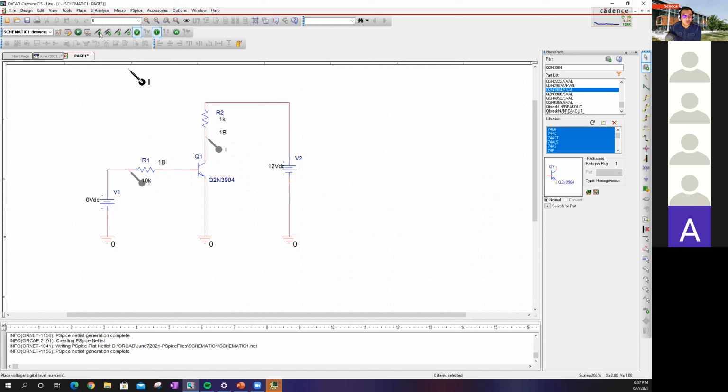And then we also want to know the voltage, let's say the voltage of IB. So we'll put it here, and then we want to know the voltage of VCE. VCE is kind of hard because there's a C here and there's the E here. So we need to use the differential marker. We put one on the C and one on the E. In this case, I put one here and one here. Right? Makes sense so far? Yeah, good. Okay, and then we'll play it, and then we'll show a simulation, which is over here.